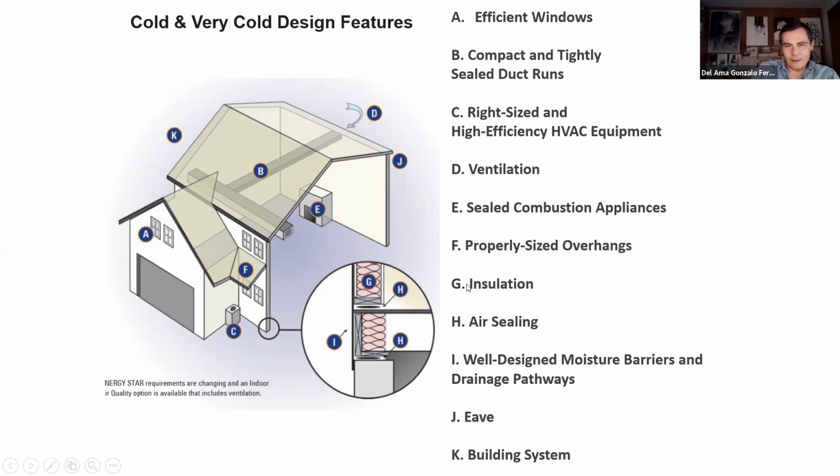Well, let's continue. I don't comment on this so far because I want to go over the insulation. We need to design the right thickness for this insulation. This is the thermal insulation, this material we have here, and we need to design the correct thickness. We need to increase the thermal resistance and reduce the thermal transmittance.